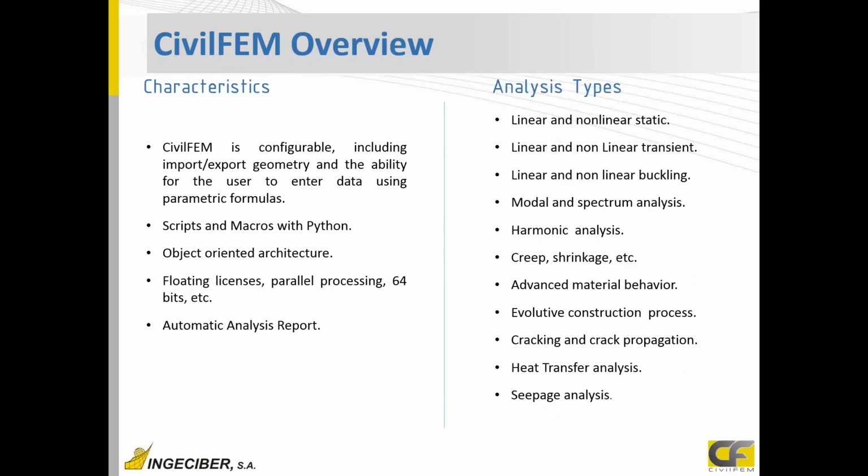The main characteristic of CivilFEM is that it is a very customizable software. We can import and export geometry, and we have the ability to enter data using parametric formulas, and scripts and macros with Python. We want to stress this feature because it's a very powerful capability we have. Everything you see in the graphical user interface can be performed by a Python macro script.